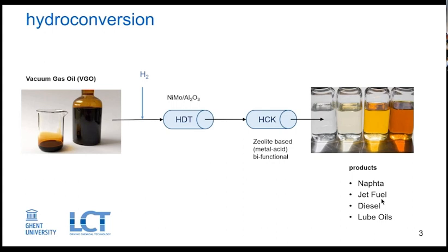And there is a second stage, which is typically known as hydrocracking, with a catalyst with a double function, an acid function and a hydrogenation function. It's here where the hydrocracking reactions take place, transforming the molecular structure of the mixture. It's here where it's possible to go from a mixture of 1,000 heavy molecules to a mixture, again, of 1,000 but lighter molecules.